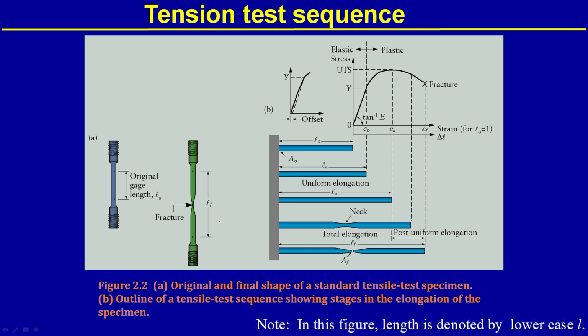So, materials which are likely to be brittle or likely to show brittleness must be tested using compression setup. Tensile testing is no good for them. Tensile testing is useful for material which show ductility. This is a snapshot of the tensile stress strain curve. You can see here nicely the elastic plus plastic portion and the different stages of tensile testing for a sample.